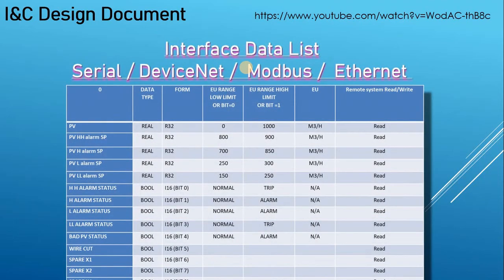Now, once you have this, you have to create another deliverable, which is the Modbus. Let's say we call it Modbus here because we assume this is Modbus. You will explain exactly what data you receive or what data you will write, the format, and sometimes for different types of communication, you specify how often you will update your data. Let's say if you have a scale, how often you will read the scale, what you are going to do with this data, and so on.